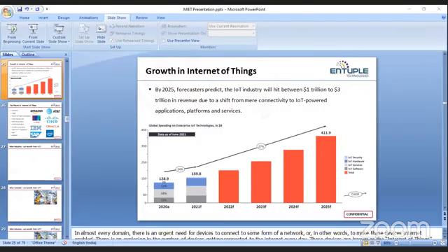As I mentioned, a temperature sensor doesn't need to transfer the information every time to the cloud. It can send the information to the gateway, and the gateway itself can take a decision. If the gateway is capable of taking its own decision depending on the data it receives, then the gateway itself can trigger an alert whether to turn on or turn off the air conditioners. So basically the gateway is responsible for device to device communication or device to cloud communication. It's typically hardware just like the Wi-Fi router we use in our home.